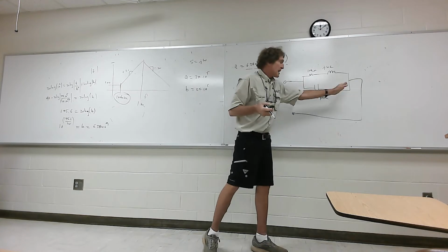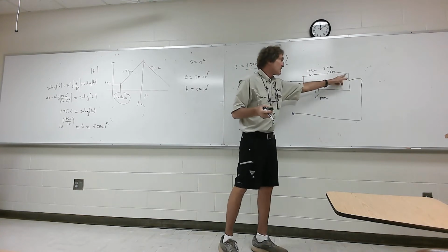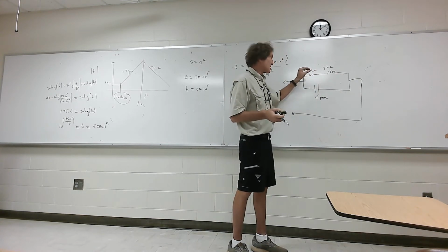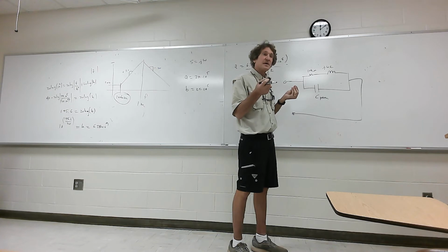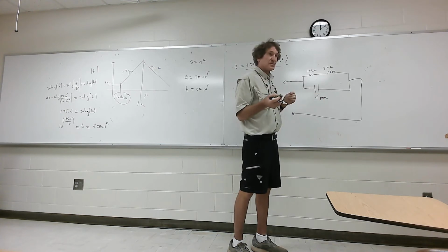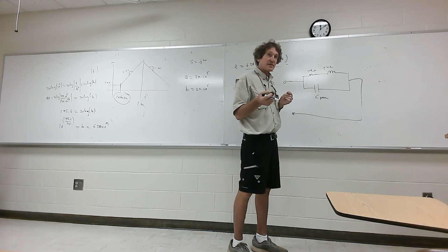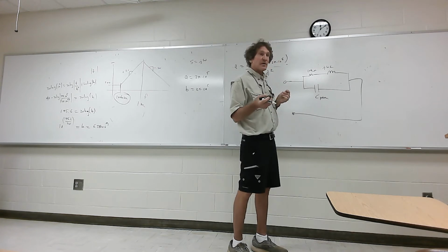The reason you're going to have that is because anytime you drive current through here, you're going to develop a voltage, and anytime there's a voltage difference between 2 points, there's inherently some charge difference, and that means there's a capacitance that's used to represent that effect. Y'all follow me, class? Now, at very low frequencies, this looks just like a resistor, 100 ohms.